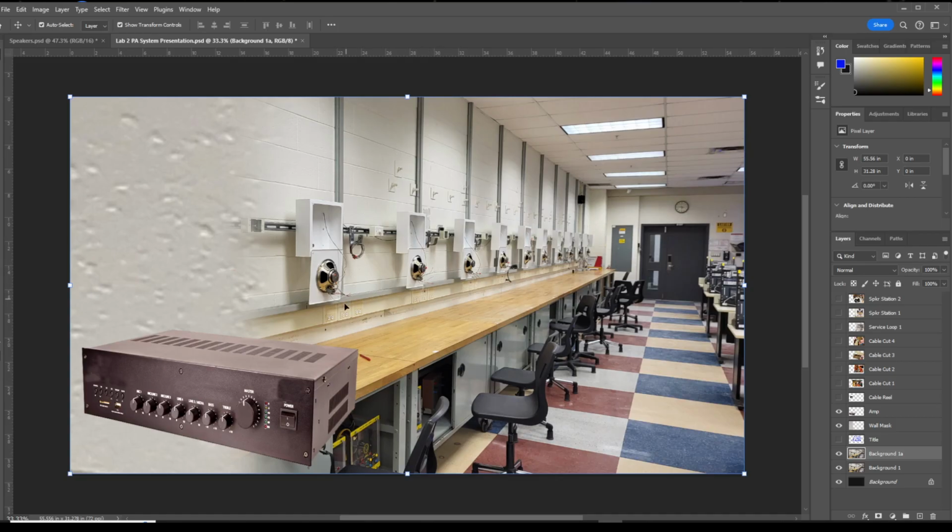All right? So starting fresh, we're going to place a wire box or cable reel somewhere in this area right here, and we're going to pull the wire all the way through the back. You're probably going to run this behind the speaker stations and hang the wires on the J-hooks, and just keep going until you reach the end. Then you're going to tie that end of the wire to something solid.